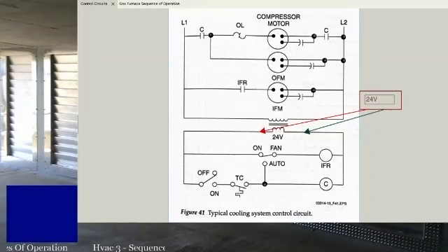Same thing could go for commercial systems. If you're trying to control humidity in an environment and it's cycling relatively frequently, it may help to switch that to auto if at all possible, depending on the system, to lower that humidity down a little bit. So it's just something to keep in mind. I have actually seen a few people solve some mild humidity situations like that in the last year or two. So on isn't necessarily a good option in cooling. It's generally a perfectly fine option in heating.